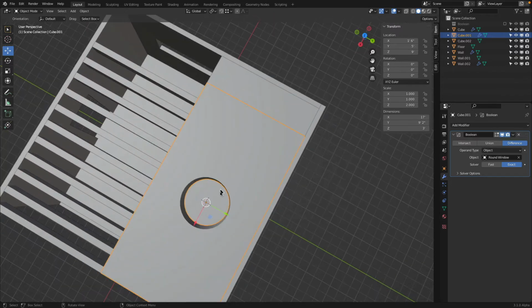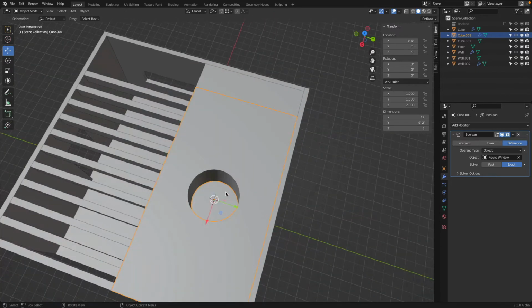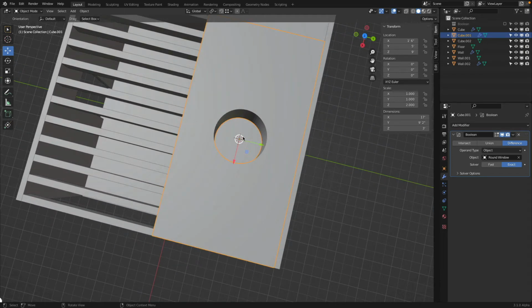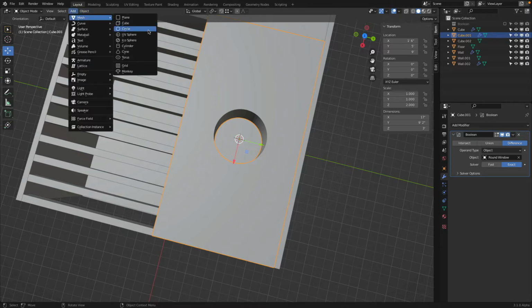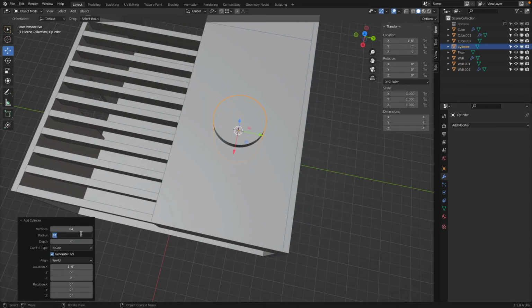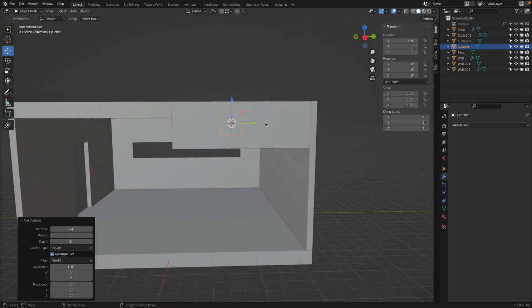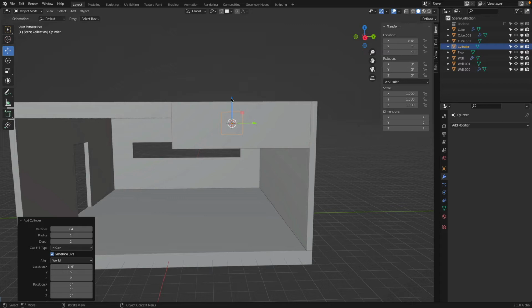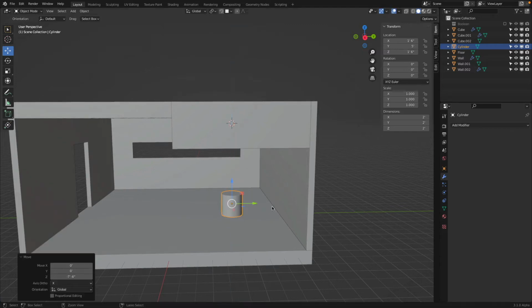When I look through here on the bottom, I would like to have another cylinder. How do I perfectly position this? Because I have the center point here and my cursor selected or positioned, I do the same. There. Radius 1, height 2 feet. Very good. And base, bring this down, hold control, there we are.